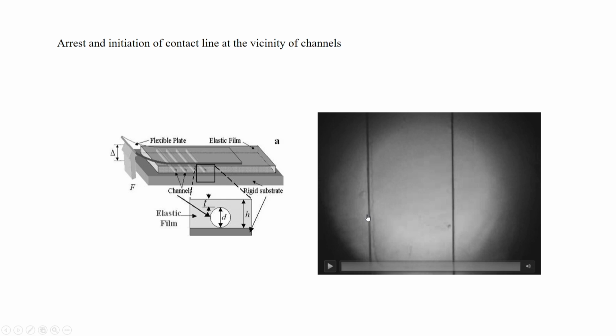So what it means is that the surface of the adhesive is smooth, no features, but we apply this elastocapillary effect that leads to this kind of bulging on the surface, which is reversible of course. But this bulging effect, or this elastocapillary effect, leads to this kind of crack arrest and initiation at the interface, leading to this enhancement in adhesion, because you need to apply load in order to go over this channel crack arrest, to move this arrested crack.